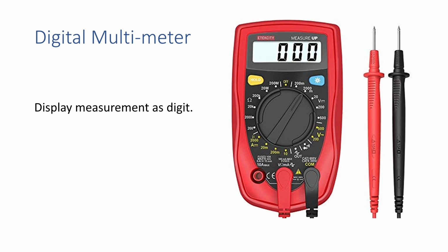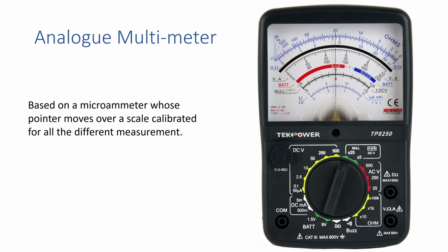So when using as a voltmeter, it will be better to use a digital multimeter since its resistance is much higher. A digital multimeter is from 1 million ohm to 10 million ohm, compared to the 200 kilo ohm for an analog multimeter on a similar range. On the other hand, it is easier to follow a slowly changing voltage by watching the needle on the analog display.